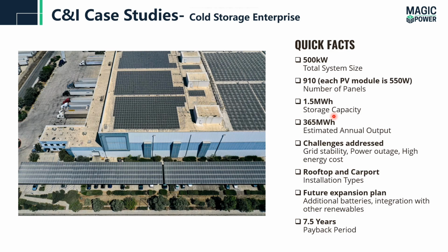If we talk about the challenges addressed for the client before installing the system, the grid was not stable, power outage was a big issue, and there was high energy cost. The installation type of the solar panels, as you can see in the pictures, is rooftop and carport. In the future expansion plan for this project, yes, additional batteries can be installed with the energy storage system to enhance the storage capacity. It can be integrated with other renewables, and the calculated payback period for this project is 7.5 years.